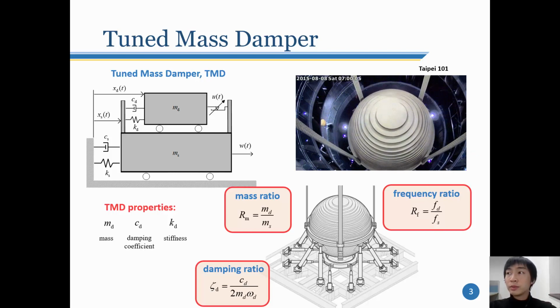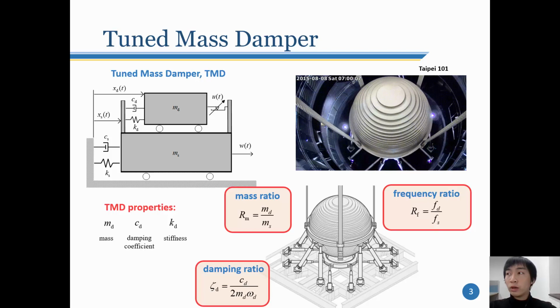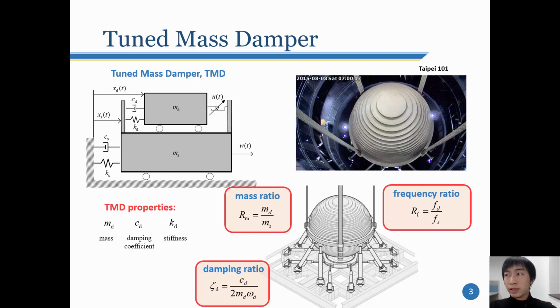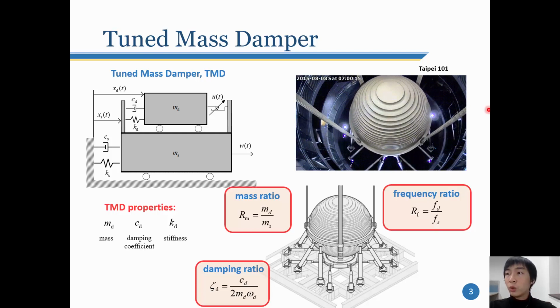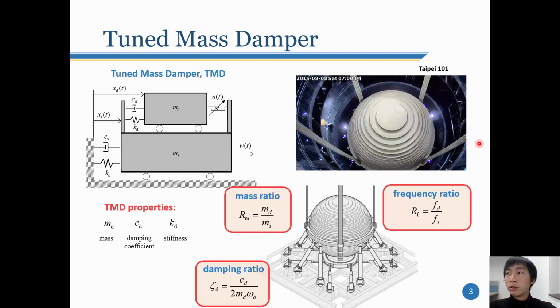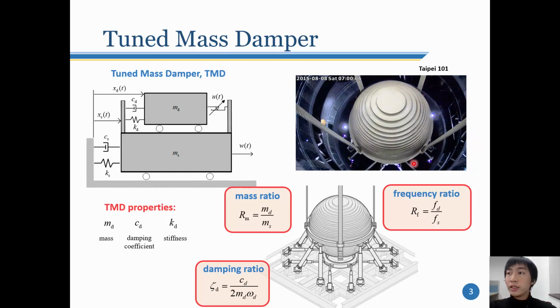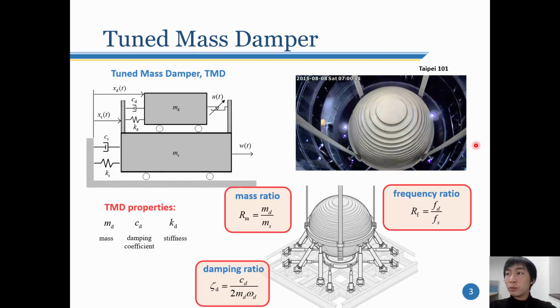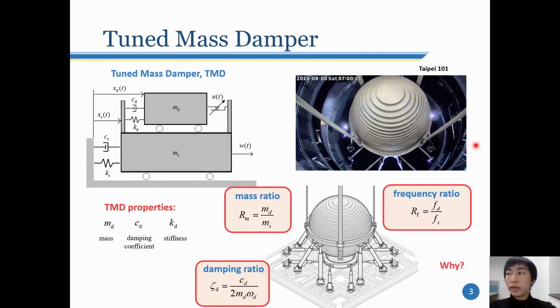In Taiwan, the tallest building is the Taipei 101. In this building, one big suspension-type tuned mass damper is installed at the top of the building. When the Taipei 101 structure encounters a typhoon or some large wind loads, this giant mass ball will start to sway to reduce the structural vibration. But while the swaying mass ball can reduce the structural vibration,